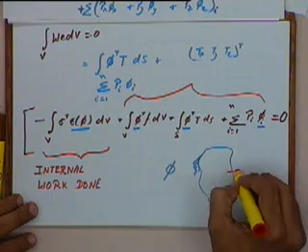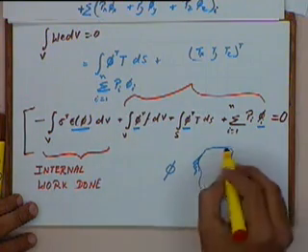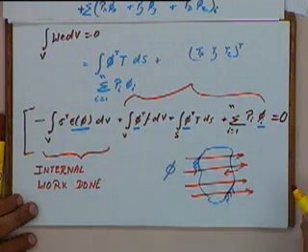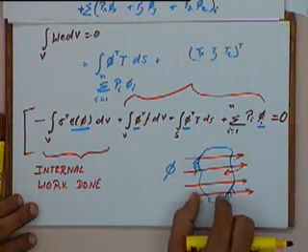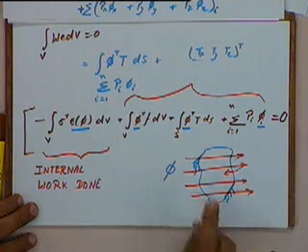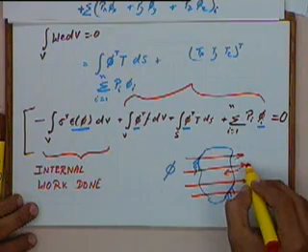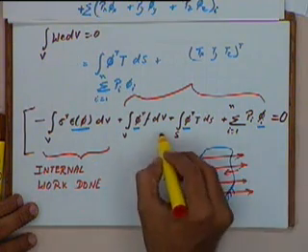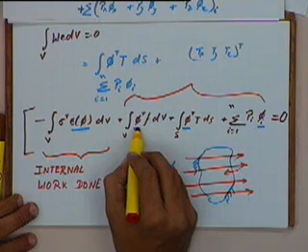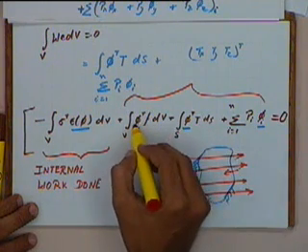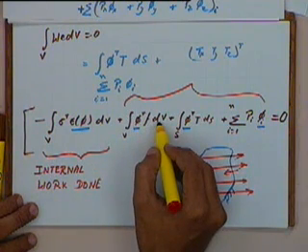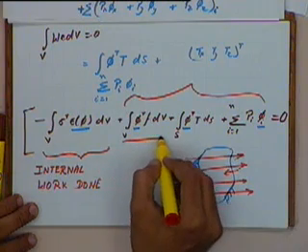Okay, let us say if I have some point load over here, or if I have some body forces acting like this, and I try to give this object a virtual displacement, okay, then the work done against these forces, against these body forces, will be given by this force multiplied by the distance. Okay, they are the body forces multiplied by the virtual displacement we are giving, and we will integrate that over the volume. So this is the work done against the body forces.